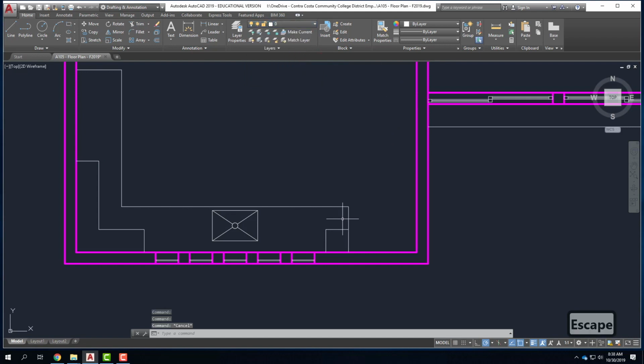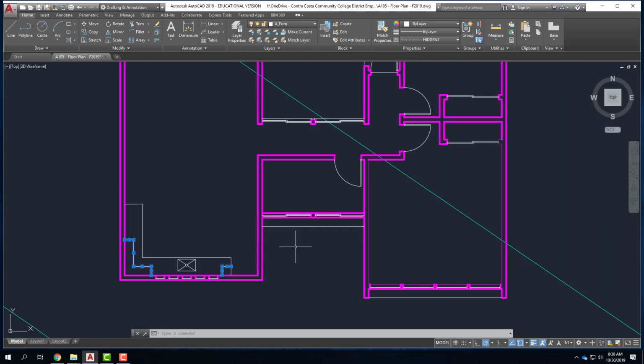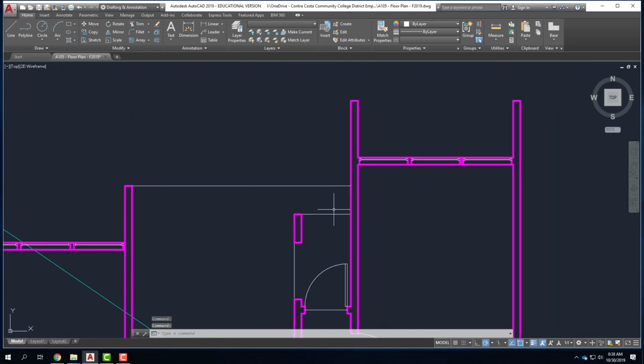There it is. Now, here's where line types come in. These upper cabinets, because they're above the plane where I cut, need to be dashed lines. So I'll select those like that, and then I can come over here to the properties, go to my line types, and choose Hidden Two as a line type. Again, they're not going to show up here, but I can specify that now, and then when we get to paper space, it'll show up. Furthermore, these overhangs, like this and that, are also dashed lines, so I could go in and change those to Hidden Two as well.